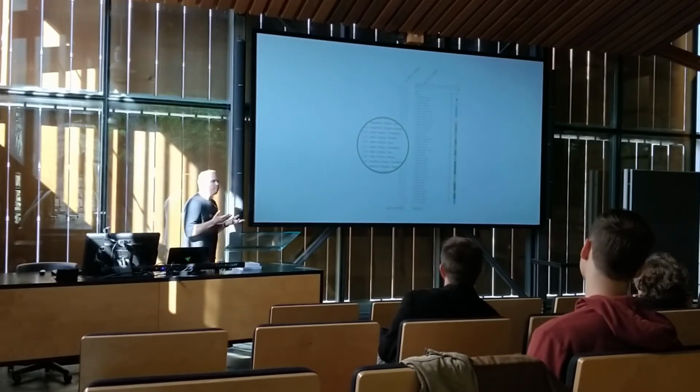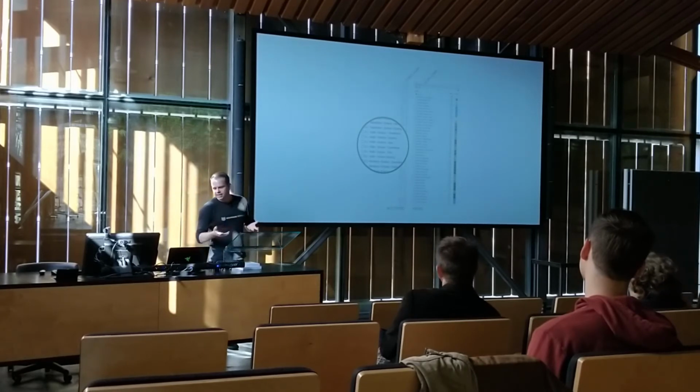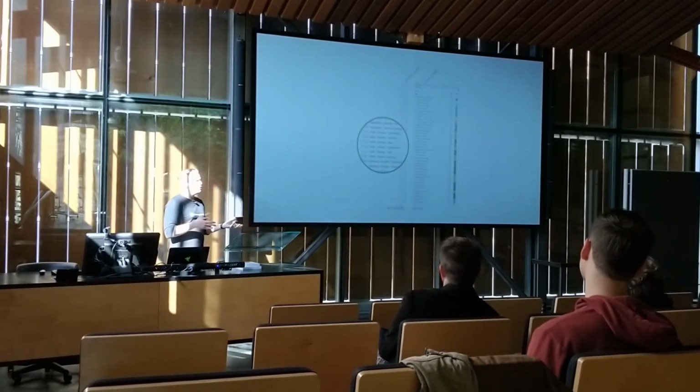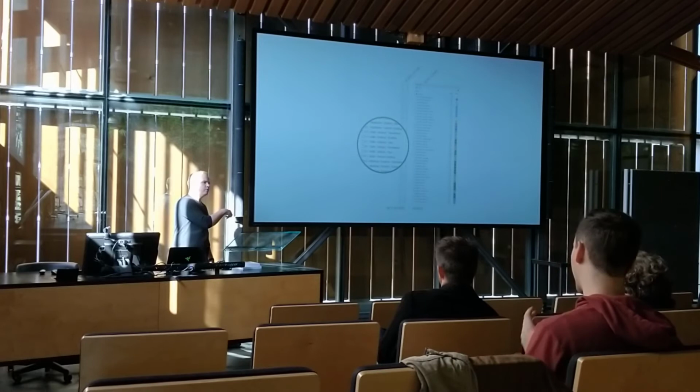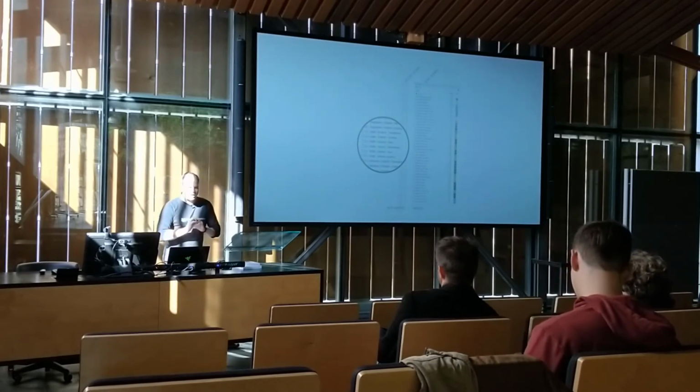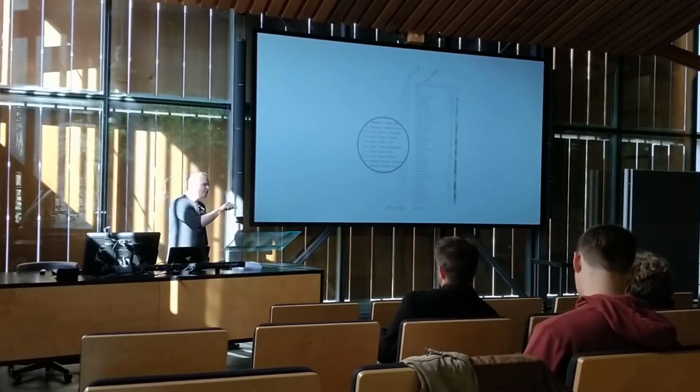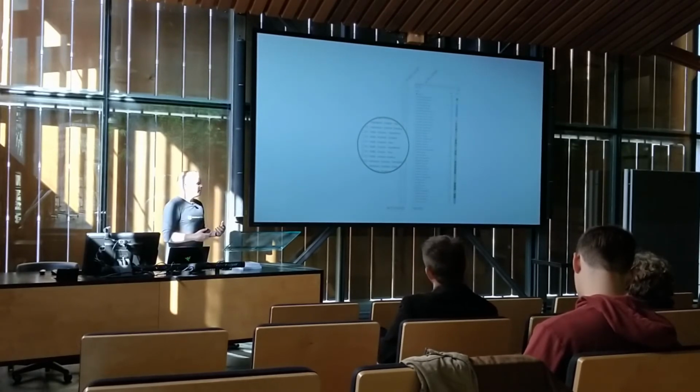Furthermore, we have these things called model organization guides, and they're on the 3D Warehouse. It's a component that you can drop in your model, and it has these little tiles. Everything is already grouped for you and completely layered for you. All you have to do is put things in the right place. We've taken away the entire need to even assign layers. You just need to know how to get to where it's supposed to be and put the walls in the walls group and the doors in the doors group.